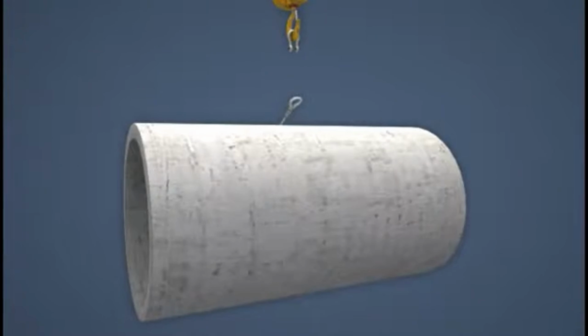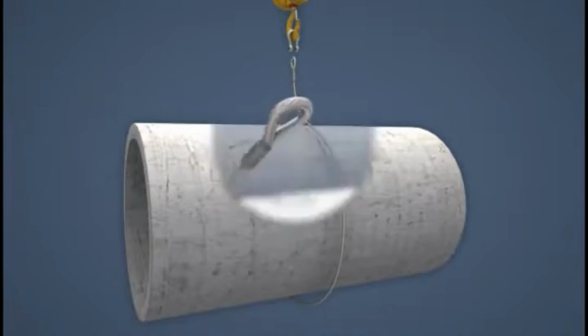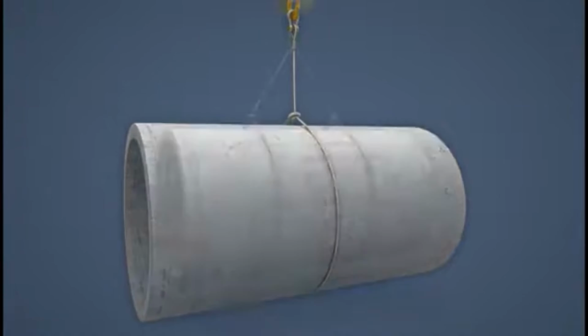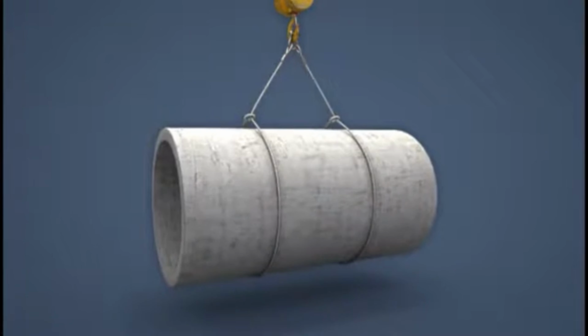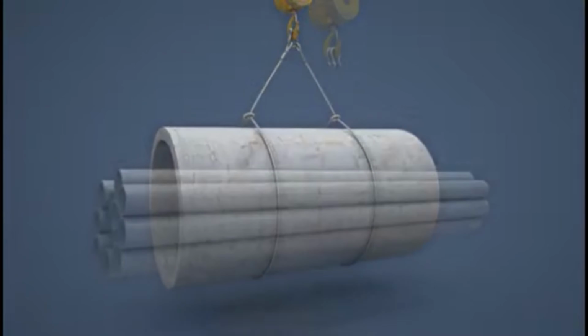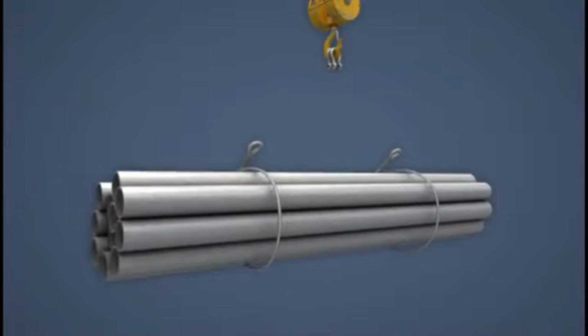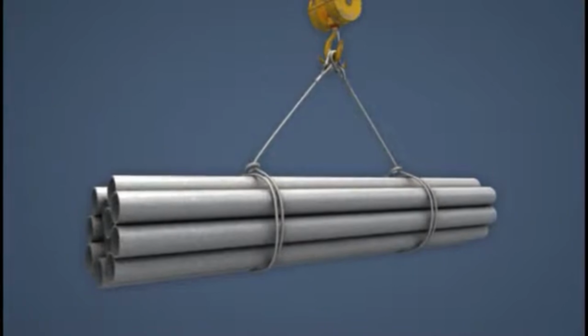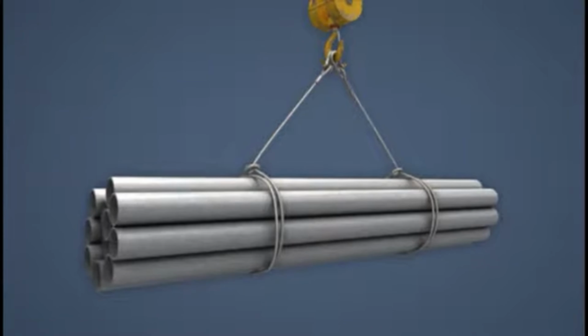Rigging a choker hitch is done by passing the end of one sling around the load and through one eye or end fitting, then attaching it to the lifting hook. Similar to a basket hitch, the choker hitch can be done with 1 sling in a single choker hitch or with 2 slings in a double choker hitch. Also, the choker hitch can be done as a double wrap choker hitch, where there is an additional wrap around the load. This creates a gripping effect and is useful for carrying looser loads.